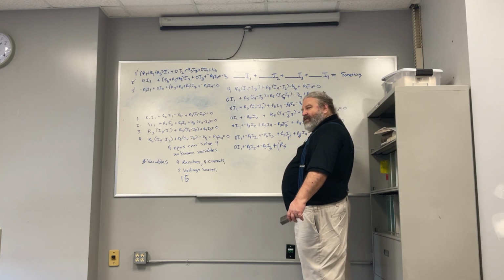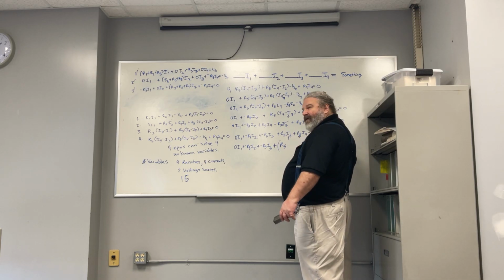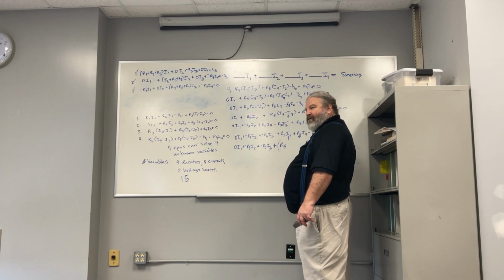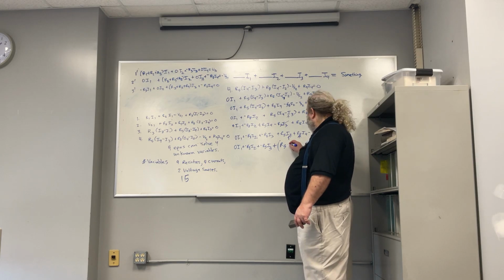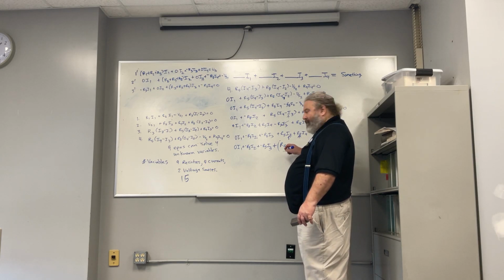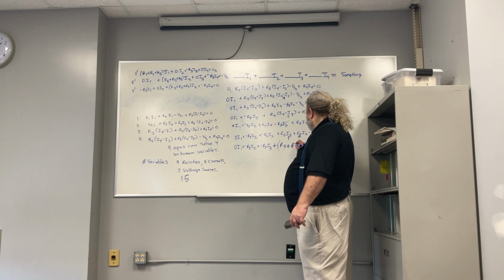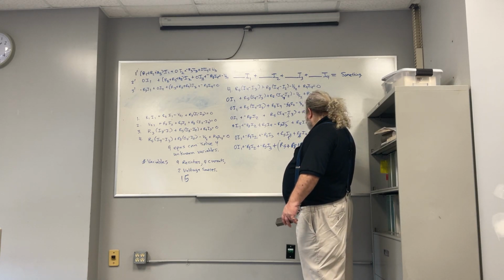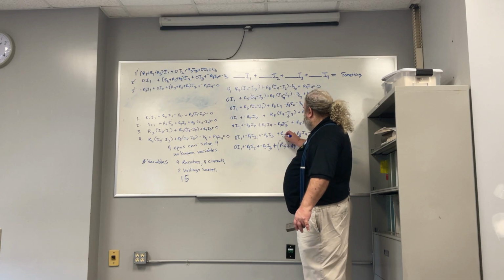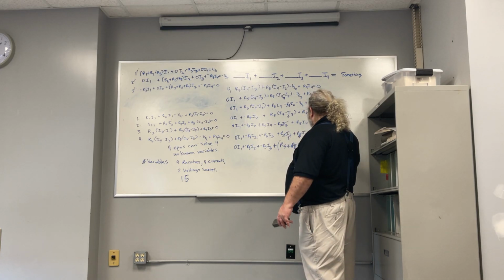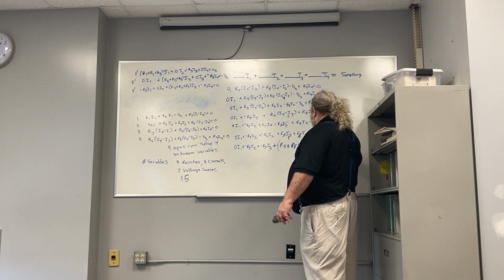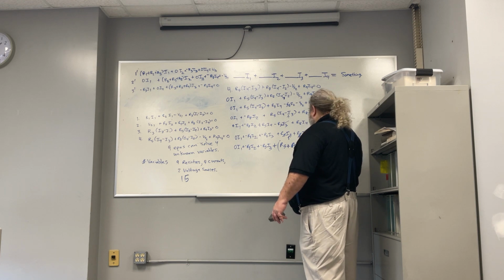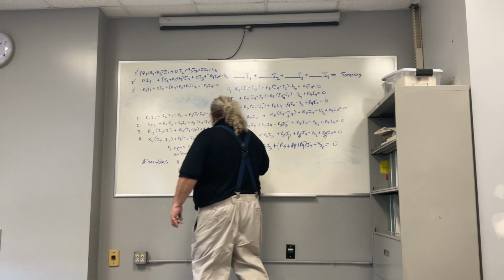Each of these has to be added together, right? R5 plus R8 plus R9, and all that is times I4. Now, just because I know I'm done with them, let me put these through. I still have the minus VS2, and I have equals 0, right? So we're almost there.